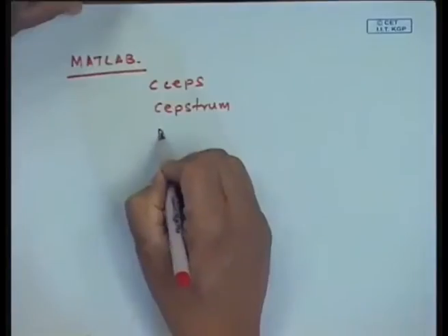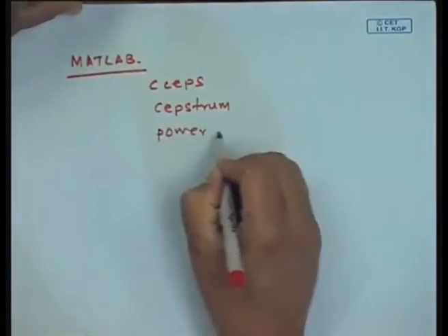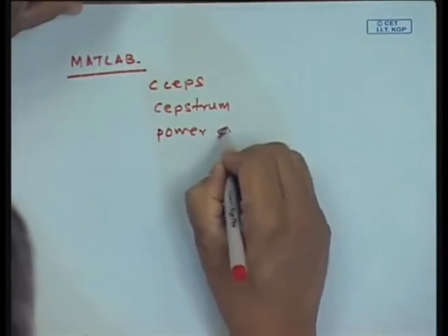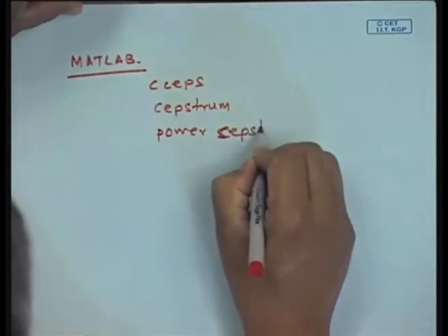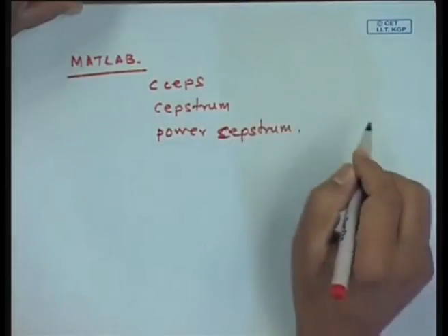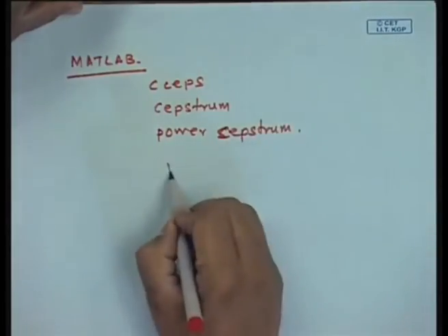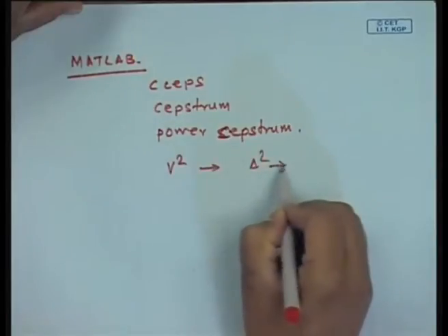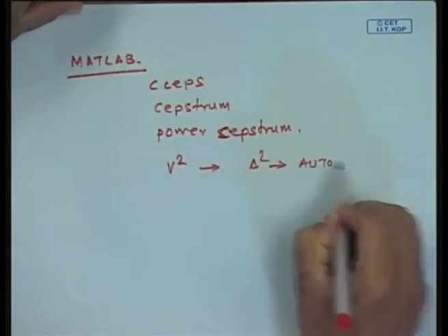So, there are many ways by which people represent the data out of a cepstrum. Okay. And sometimes they call it a power spectrum. If you are dealing with a power signal and auto power spectrum, then you will have a power cepstrum. Okay. Because if there is a voltage square term or an amplitude square term, I can call it an auto power spectrum.